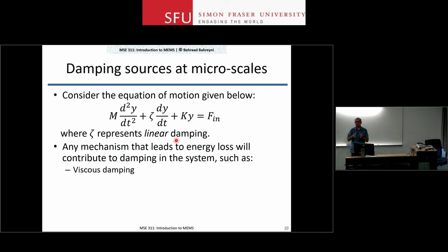That is an energy dissipation mechanism. You're squeezing the film in and out of that gap. So it's called squeezed film damping, but it's a type of viscous damping. You're basically dealing with the fluid movements, fluid interactions with your solid structure. Your only way to avoid it, obviously, is to operate under vacuum. If you get rid of the fluid, you get rid of viscous damping. Fluid in this case is gas.